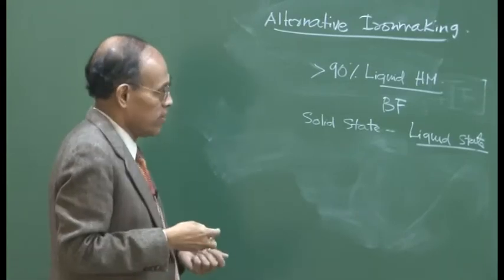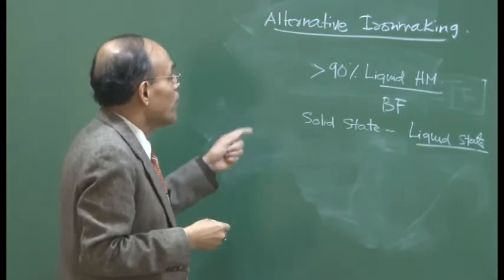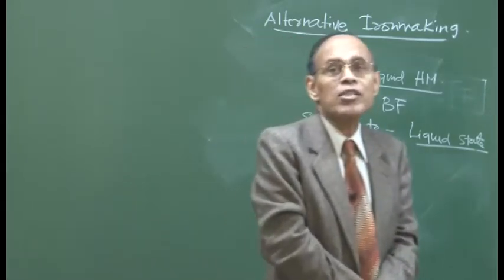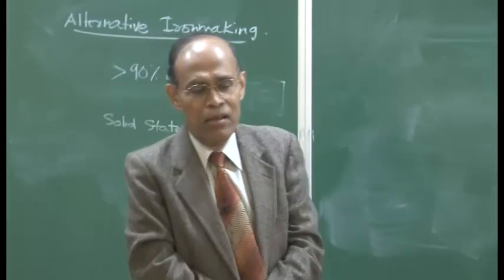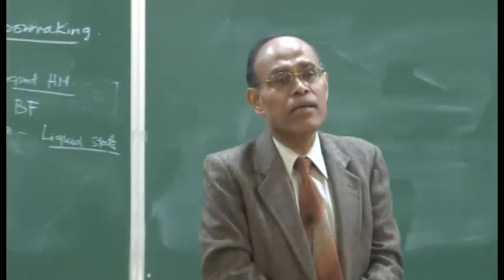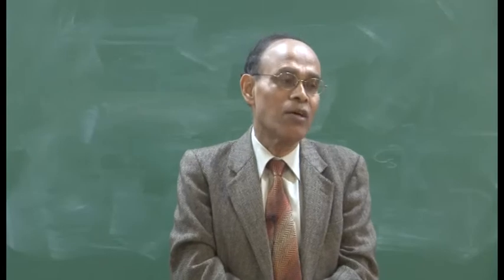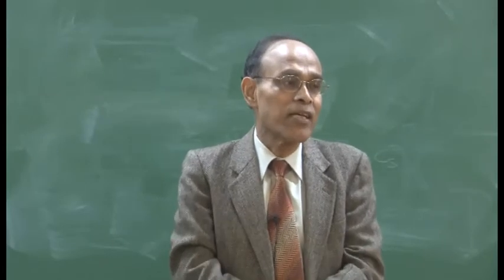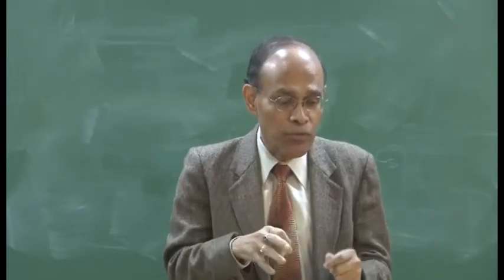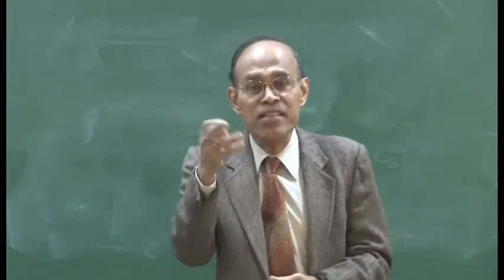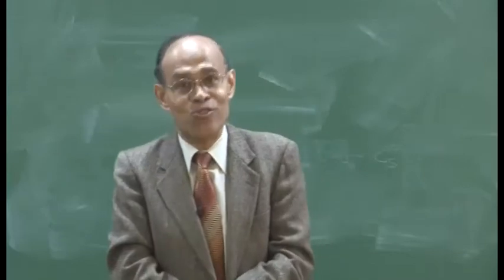On top of that, we know that in steel making an enormous amount of heat is released. For example, carbon and silicon, and as I said, that silicon control sometimes is not so perfect. So, at some point of time when you start blowing oxygen, even though the silicon and carbon oxidize, a significant amount of iron also gets oxidized.